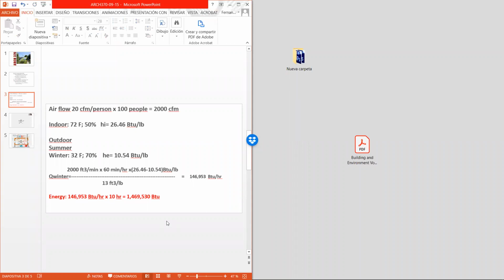So if you receive that electricity bill, 1.5 million, and this is one day, because this is 10 hours. If we multiply this times 30 days, there will be like 30 million, 40 million BTUs. We are crazy. This is the end of the world. No, it's not. Because now, if we want to turn this into therms, we know that one therm is 100,000 BTU.